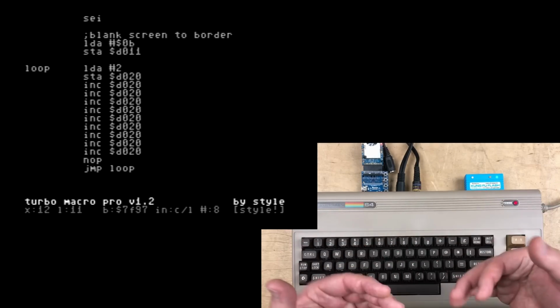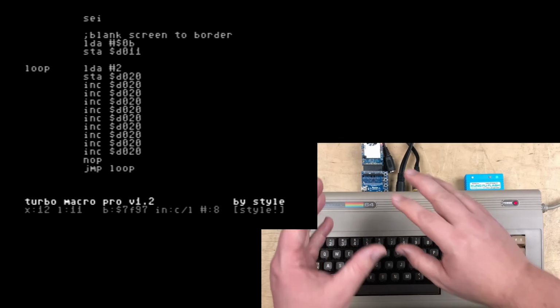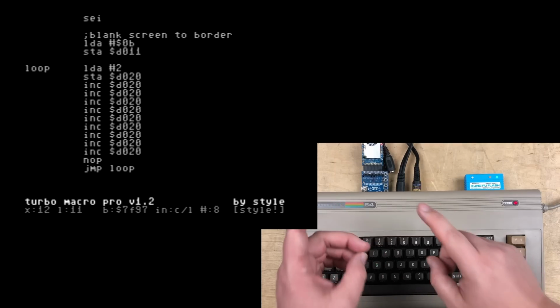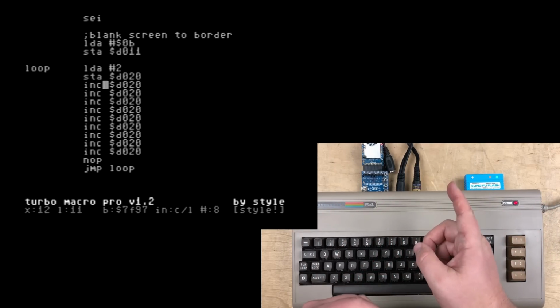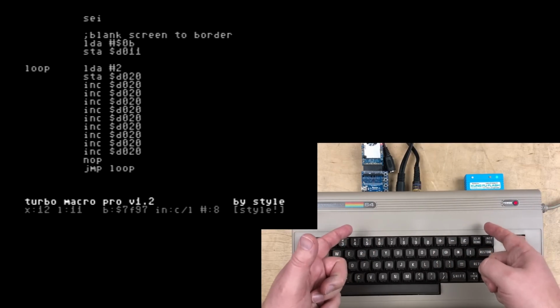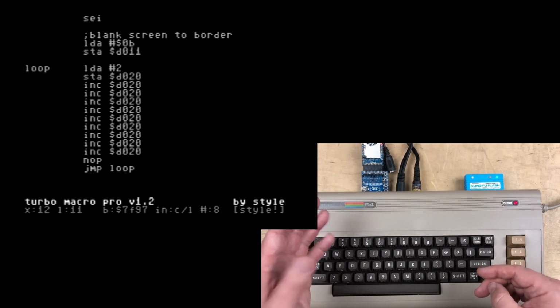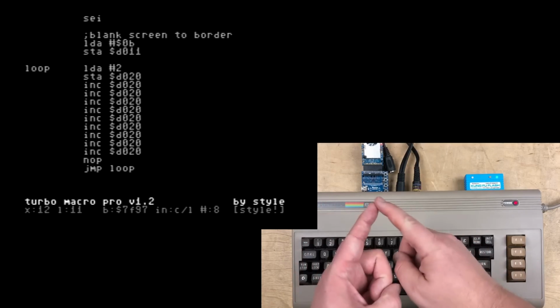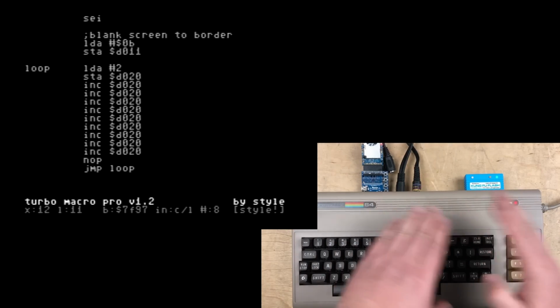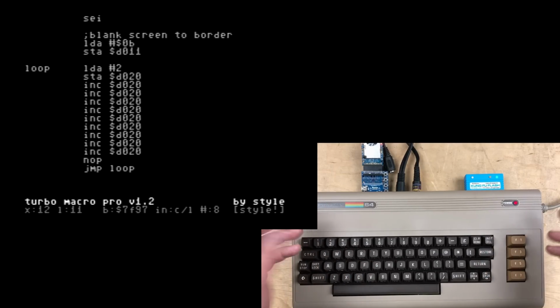But from our perspective, we don't know where red is going to be on the screen. We're not in sync with the starting position of the video. We've talked about how there's 65 cycles, again, NTSC, 65 cycles across the screen. Red could start at cycle 0, 1, 2, 3, 4, all the way up to 64. So sometimes it's not even on the screen. It might be in the borders, whatever.